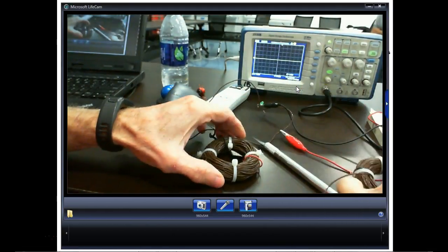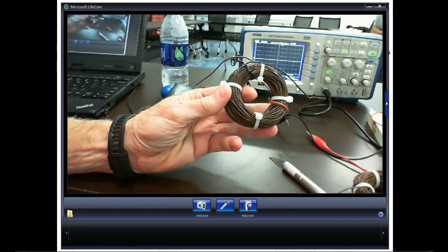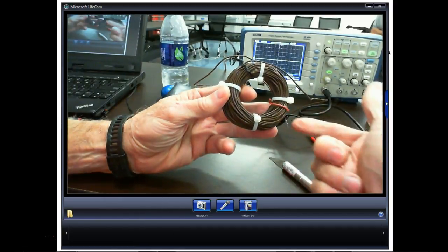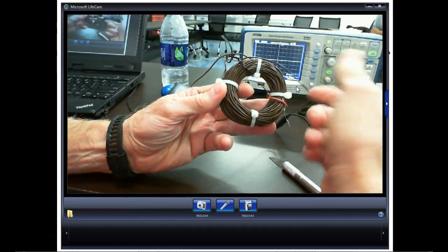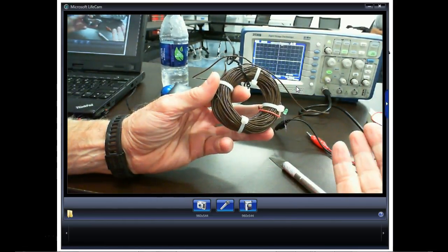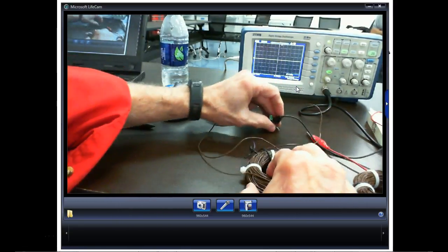Now if I bring another coil of wire in contact with that, like this coil of wire, if I expose it to that magnetic field, when it's coming out of this other core, it's going to cut this, and going to go back, it's going to cut this. I have a conductor, I have a change in magnetic field that's got motion to it, and I induce a voltage into this guy. So watch what happens.